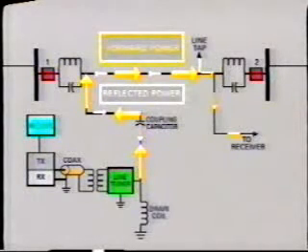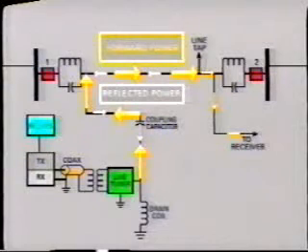Reflection of a signal can be explained by a simple and familiar analogy. When you shine a flashlight through a glass window, most of the energy passes through the glass. Some, however, is reflected back to you. The reason for this is that the glass and the air have very different optical characteristics. And when the light beam leaves the air and enters the glass, some reflection occurs. In our communications circuit, reflection will occur at any point where a discontinuity in impedance takes place, for example, where a second line is tapped into the transmission line.